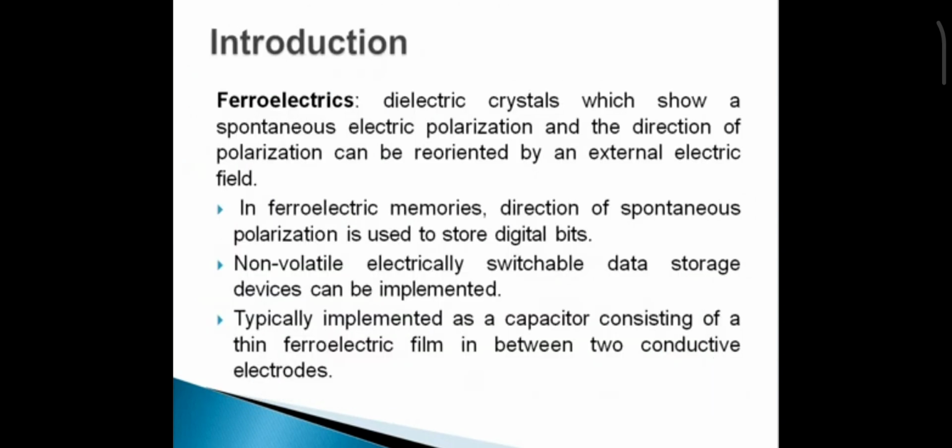Next is the introduction of the ferroelectric. Ferroelectrics are dielectric crystals which show a spontaneous electric polarization, and the direction of the polarization can be reoriented by an external electric field. In ferroelectric memories, the direction of spontaneous polarization is used to store digital bits.